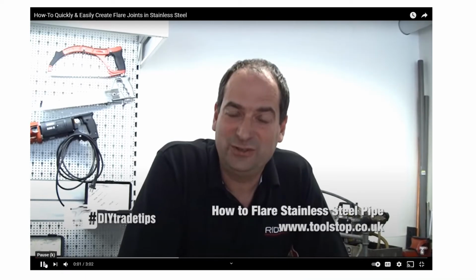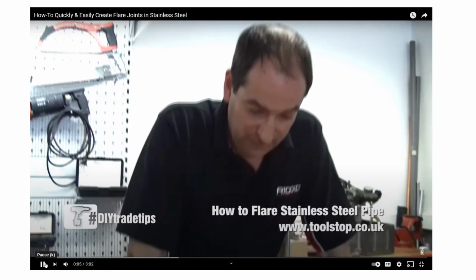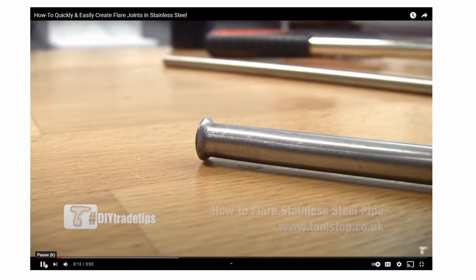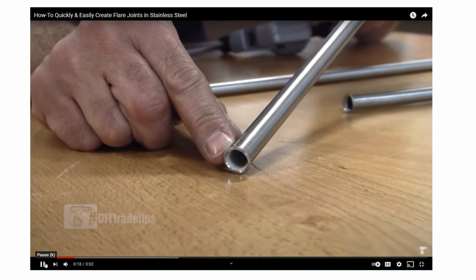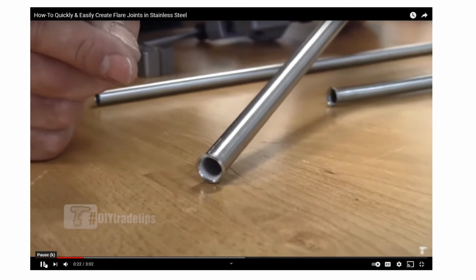From Ridge Tool, continuing with our stainless steel theme, we're going to look at flaring. So, what's a flare? Well, a flared end is this kind of thing, okay? They can come in two angles of flare, 45 degrees as we've got here, or you can have 37.5 degree flares. Quite simply, it's just a way of jointing the pipe using the fittings.